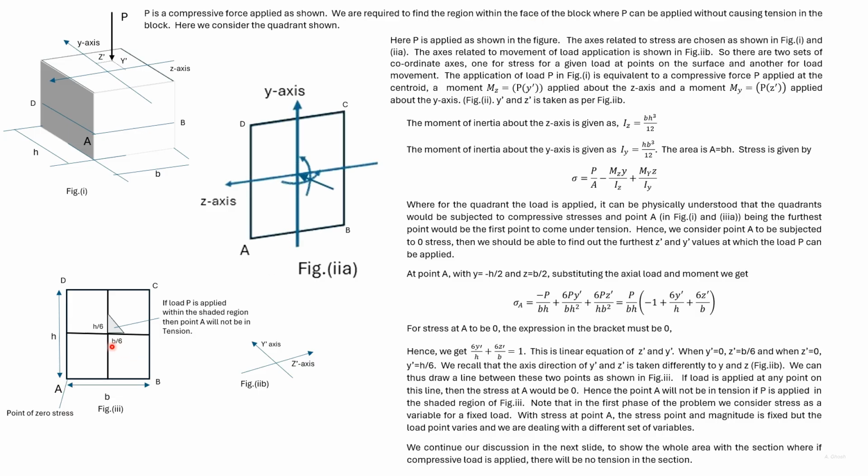If the load P is applied within this shaded area, then this rectangle will be in compression. If the load P is applied outside this shaded area within this quadrant, then part of this rectangular portion will be in tension.